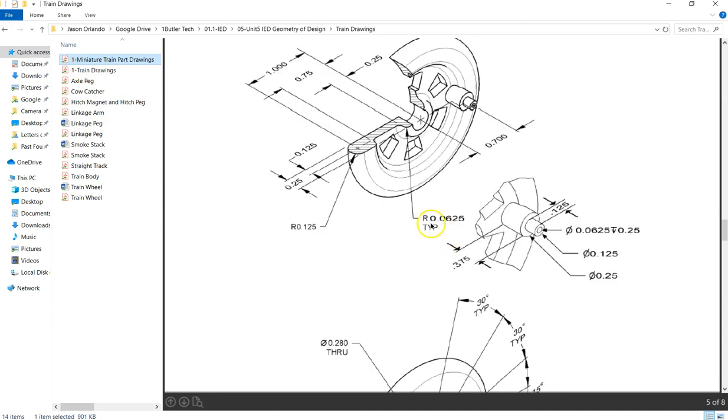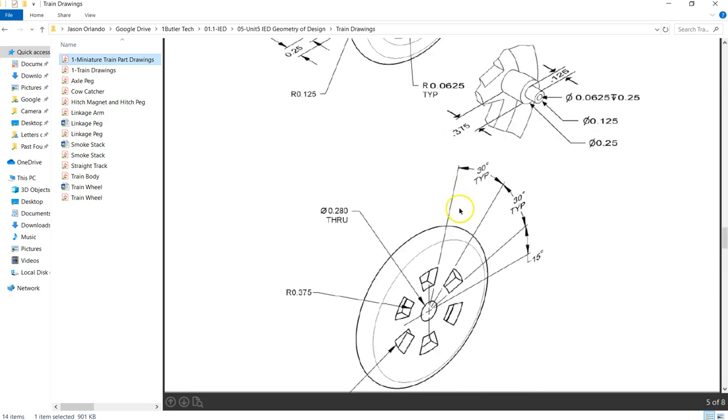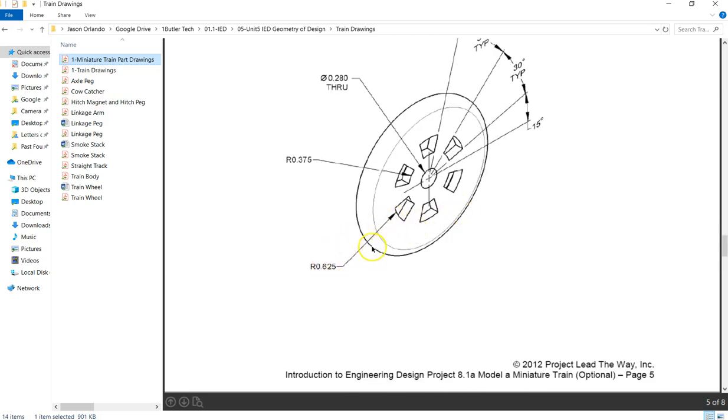So, finishing the train wheel involves these little cutouts, okay? And adding in this little piece, this tab in which the linkage arm is going to connect. So let's do these cutouts first, and it is this view that's giving us the best view of the geometry. I see leader lines giving me arcs to understand the radius of the outer arc and the inner arc right here. These are all concentric to the center.